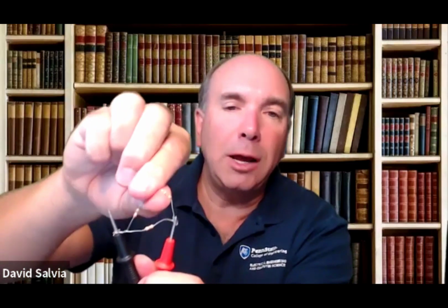So once again, we see that depending upon which 2 terminals you measure, that's going to change which resistors are in series. In this case, these 2 resistors are in series, and then that combination is in parallel with this one. And you could actually work the math out yourself, with this being 2K, 6.8K, and 3.9K. 3.9 plus 6.8 in parallel with 2, you should get something close to this, with the understanding, of course, that these are the nominal values.